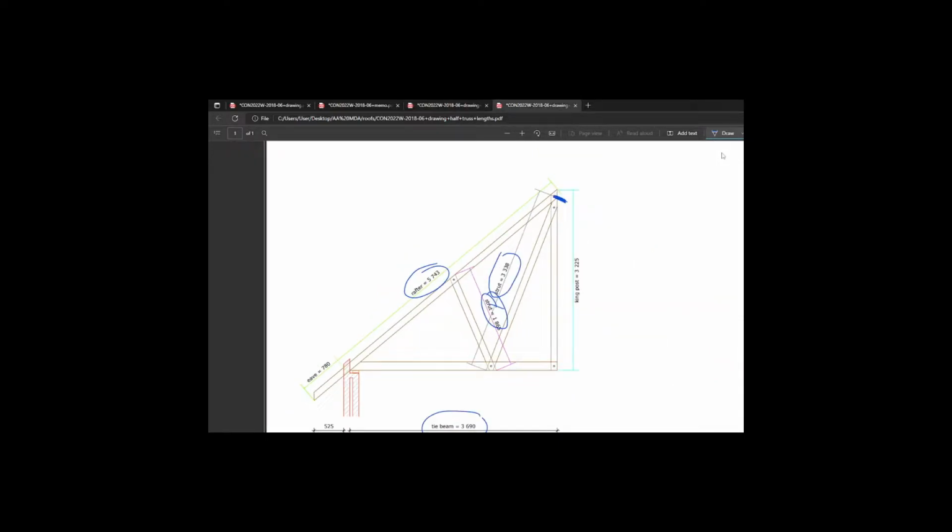And what you also notice, which will come up just now, is that we have had to add a king post because basically there'll be nothing holding up this top section. So this king post is going to hold up our rafter, which basically wants to collapse like this. I mean, sure, we have some struts, but it's not enough. Anyway, short strut is pretty straightforward. That's given, well, not given, scaled.